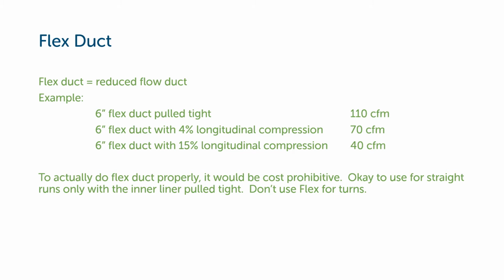If you were to really stretch it out tight and support it every 48 inches with a strap, I don't think I've ever seen this. But if you were to do it properly, I would submit that it would probably be more expensive than using regular metal duct. So here's how we see reduced flow and flex duct.